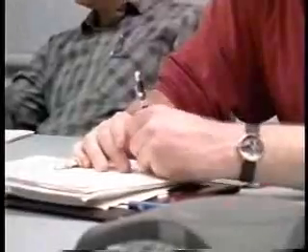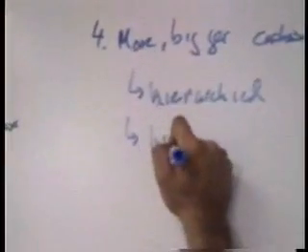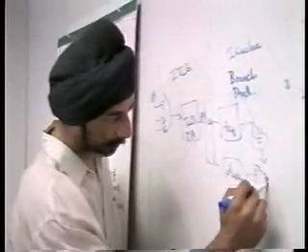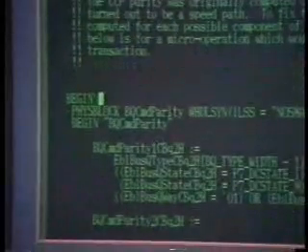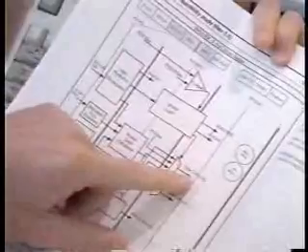Computer architects, working at the highest level of abstraction, define the overall function of the chip. They establish the microarchitecture, which regulates the timing and sequences of instructions that tell a microprocessor what to do. The design is divided into areas that perform specific functions. Each unit is assigned a logic designer, who works at the logic level to create more detailed specifications and establish hardware needs.